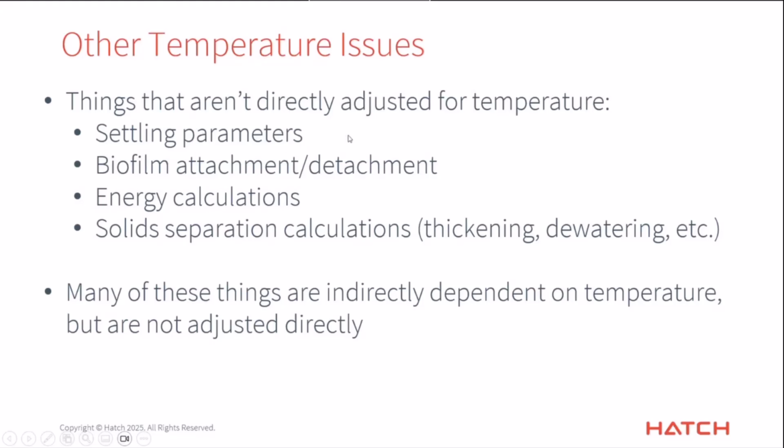The settling parameters are definitely not a function of the temperature. To make the settling parameters a function of temperature is a much, much, much higher level of modeling than we would be able to do with the regular approaches that we have in GPS-X. That's really about temperature gradient. You've got cold things mixing with warm things, and densities and falling. So that's kind of a CFD modeling issue.